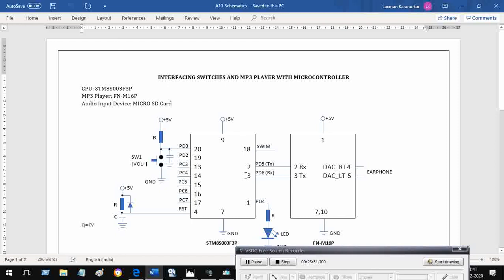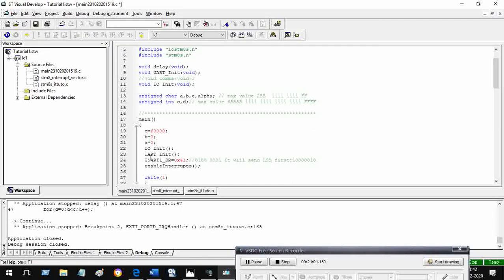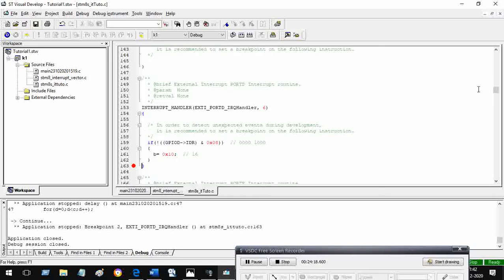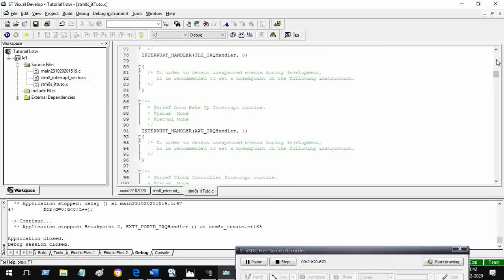We have seen it before also. Without interrupts also, we have seen how data moves in serial ports. So this is how it is. Coming back. Now I am sending 0x41 on transmit, and only once. I am not sending it again and again. And therefore we expect an interrupt to occur just once. And then what will happen? Let us see. It is here.